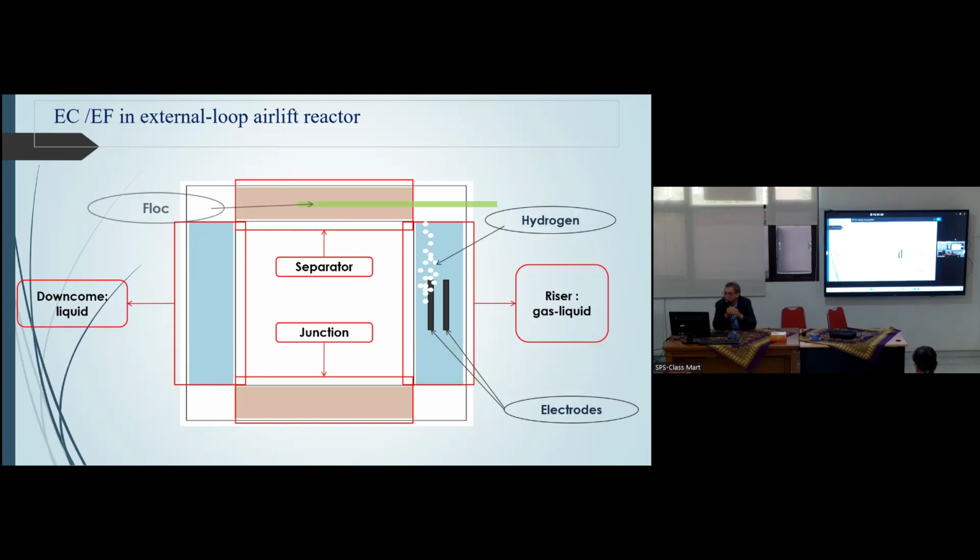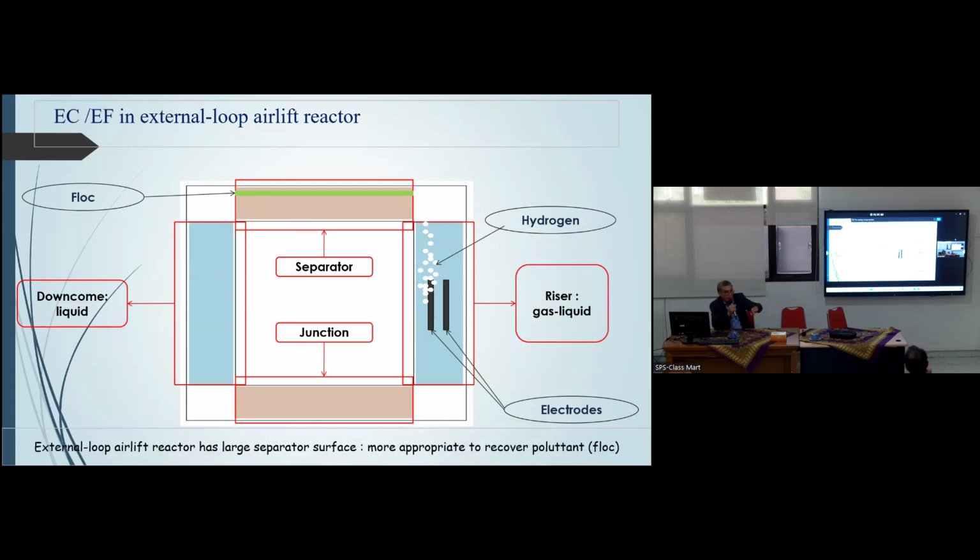Hydrogen. And we have floc. Okay. And we have induced liquid flow because we have a difference between this compartment and this compartment. We have only the liquid, so we have a great density, and in the other we have a mixture between gas and liquid. We have low density, so we have an induction of a flow of the liquid. We have agitation without mechanical power.